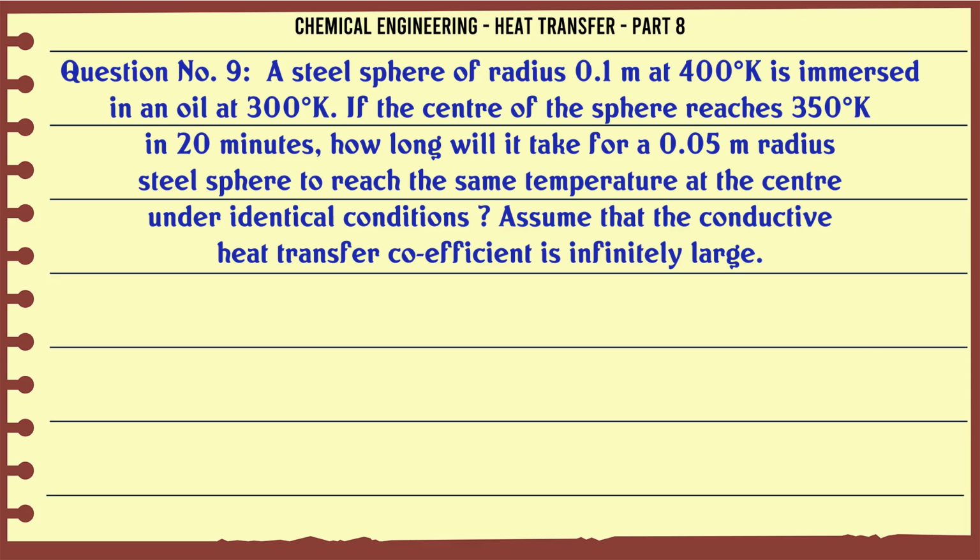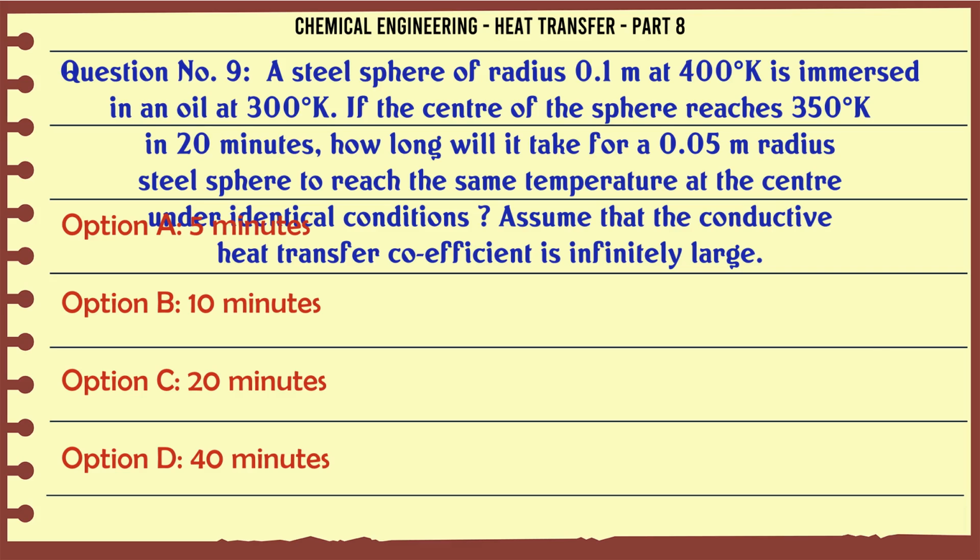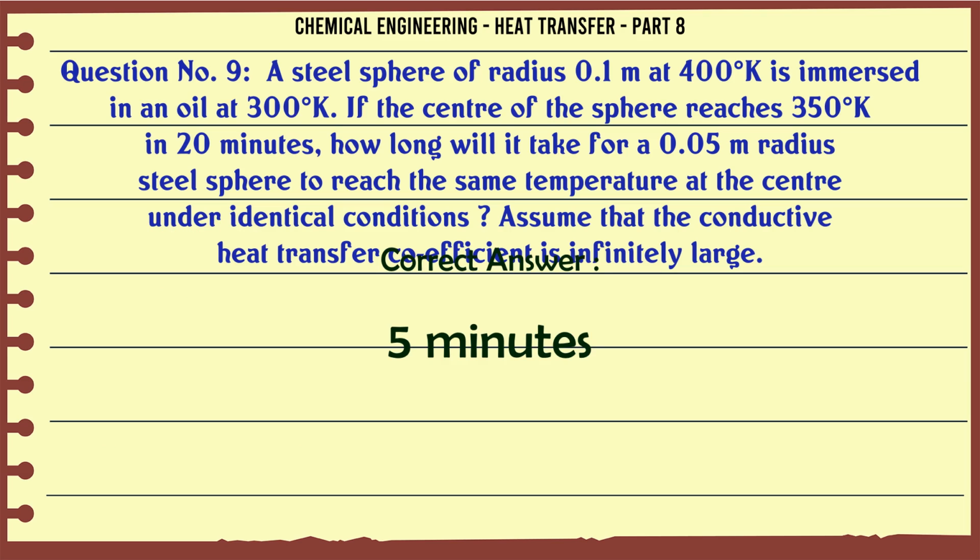A steel sphere of radius 0.1 m at 400 K is immersed in an oil at 300 K. If the center of the sphere reaches 350 K in 20 minutes, how long will it take for a 0.05 m radius steel sphere to reach the same temperature at the center under identical conditions? Assume that the conductive heat transfer coefficient is infinitely large. A. 5 minutes, B. 10 minutes, C. 20 minutes, D. 40 minutes. The correct answer is 5 minutes.